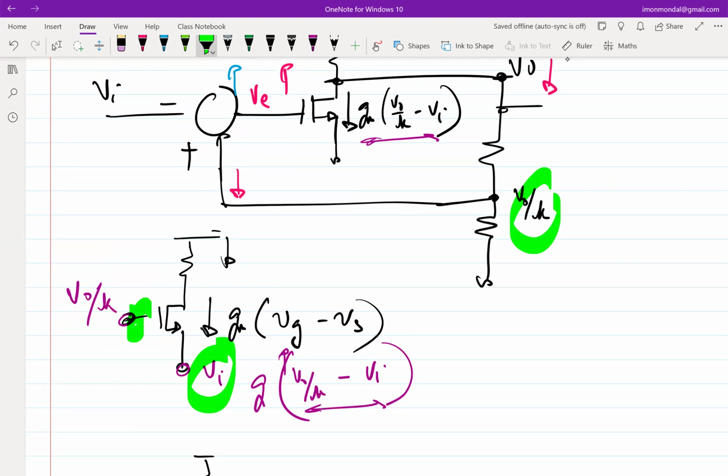Okay, which essentially means that one of the terminals is fine, one of the terminals is going to the gate, not an issue, but the other terminal cannot be the source. If the other terminal is the source, then you will draw current from the source, from whatever you are supposed to be driving into the source, and naturally the voltage will get disturbed. So we cannot use it directly.